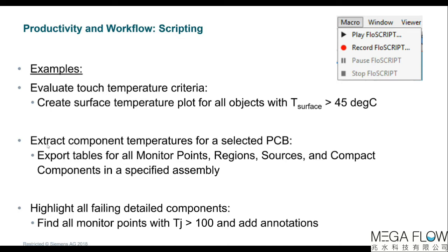Another example would be to highlight all failing detailed components. So a script could be created to find all monitor points that have a temperature greater than 100 degrees Celsius, add annotations, and create a screen capture and write that to disk, for example.